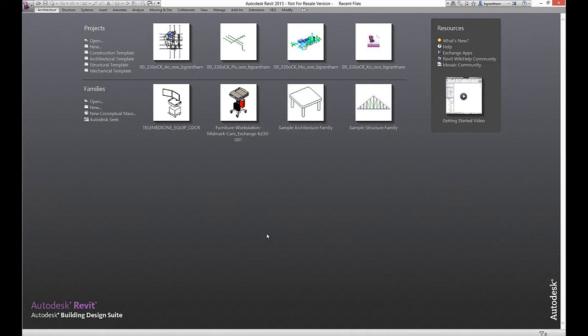Then we're going to apply that wall type in the project and then associate it with the existing CMU wall, essentially joining the two together. The reason behind this is so that all openings that we already have existing in that CMU wall for windows and doors also cut the geometry we're going to be laying out in the project after we've placed it.